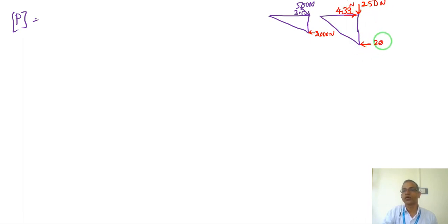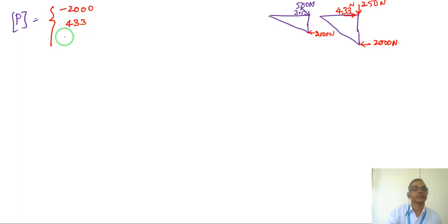So here I have 2000 Newtons. So now directly the coordinates, I have P1, which is my coordinate was the right hand side, but this force is opposite of that, so minus 2000, and second coordinate is my horizontal, so my force is positive there, 433, and third coordinate, the third force which is downward, my coordinate is upward, so minus 250. So this is P1, P2 and P3.